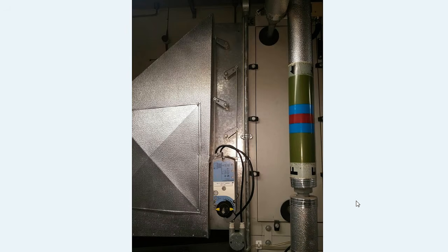And this is just a photo of one of the control units for the dampers on an AHU. And so a controls signal is being sent to tell this to change its position, and that's a small motor inside which is going to turn this, and that causes these rods to rise and fall either way. If you imagine, this can change the position of this rod here, and on the inside of the duct is the damper.